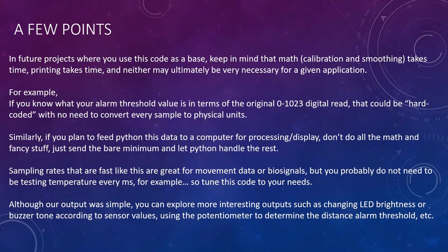I would encourage you to go look at some of the other sensors that you have, the photoresistor, the thermistor, which is a temperature sensor. Play with the potentiometer. If that one is a little too fiddly, go to Amazon and buy a $1 10K potentiometer, just like this one, but bigger. They sell them with big dials, so they're a little more fiddle-proof, I guess. This one that they gave you is very delicate, and it's hard to keep the wires on it. A lot of the stuff they gave you is very delicate, so you can always replace those parts with more robust things.